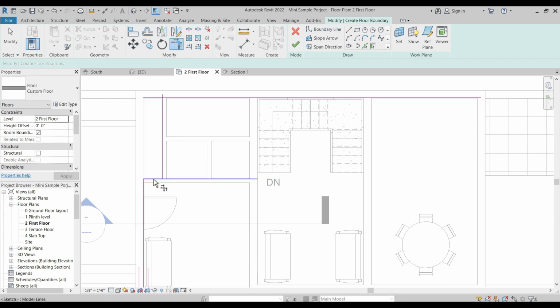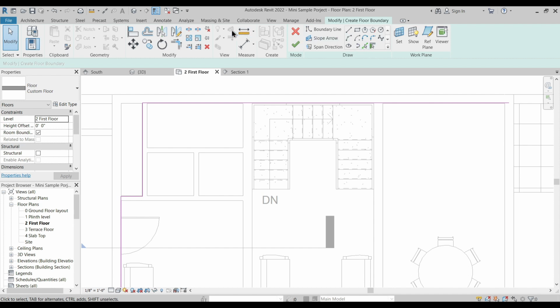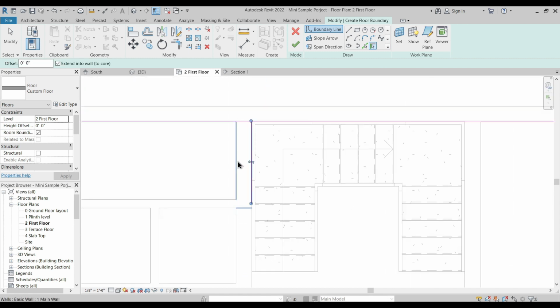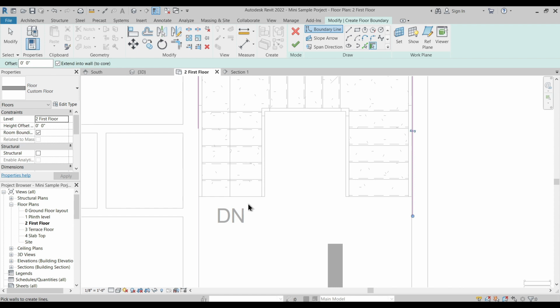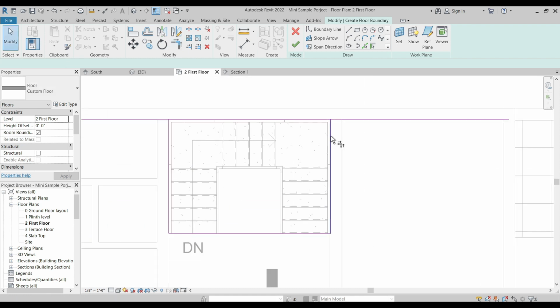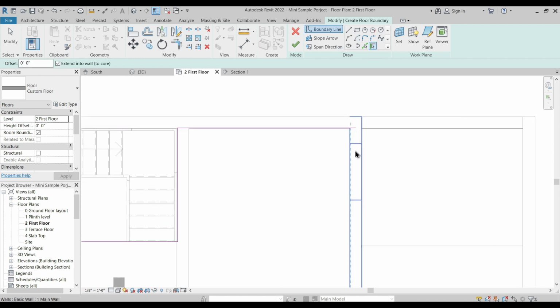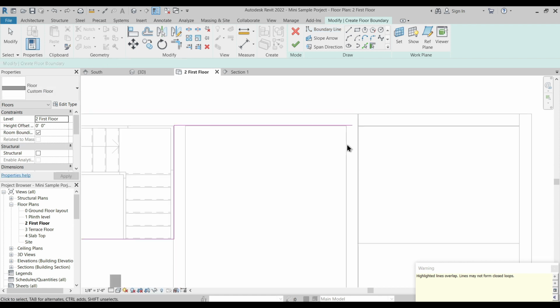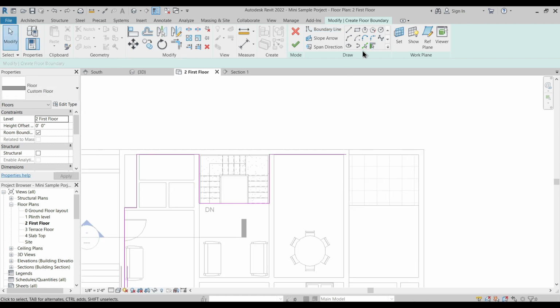I will just clear this by trim extents, and for this I will add a split line, and again I will say pick walls, and again, we will deduct the staircase portion, and I will join this, and again we'll go to pick walls and again select this exterior and highlighted wall.